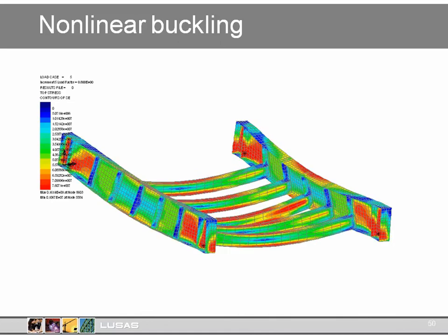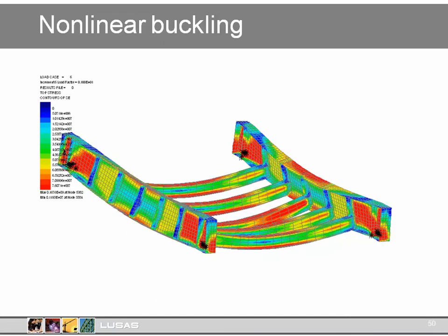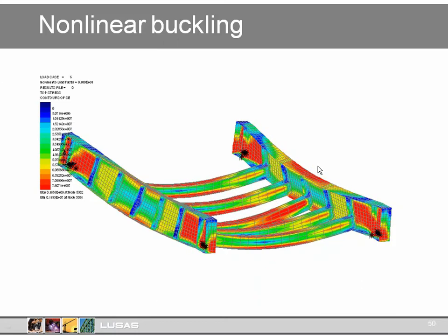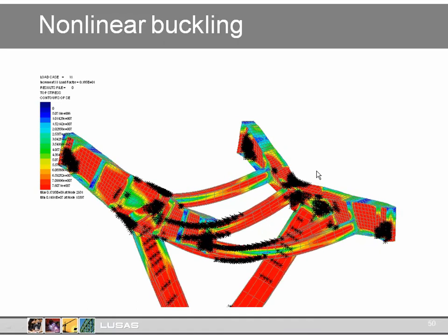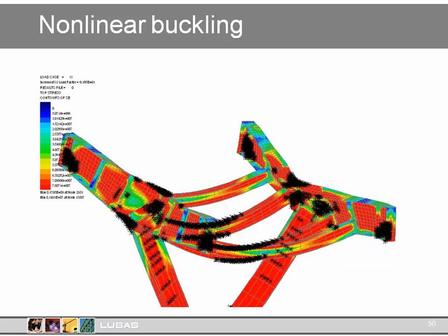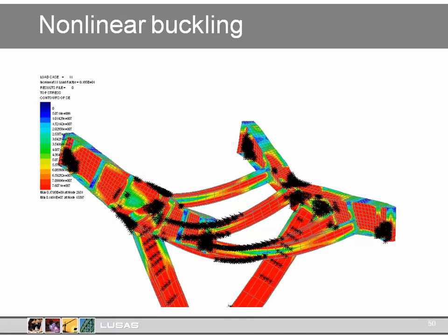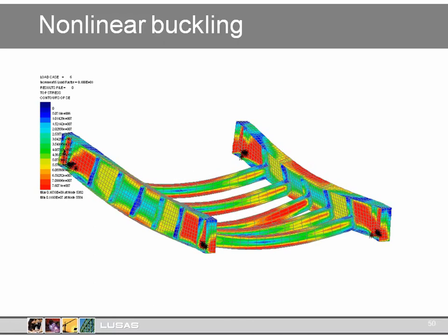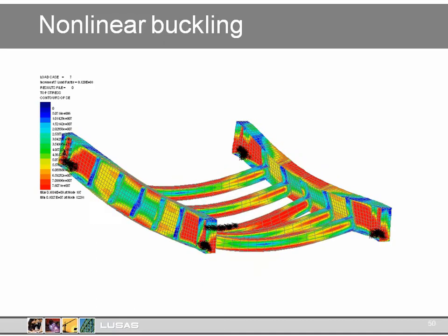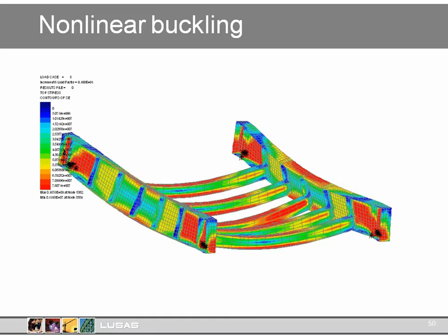And the final analysis can look something like this, incorporating geometric and material nonlinearity. In this animation, the black stars show where yielding is occurring. This kind of analysis, underpinned by a thorough understanding of finite element analysis in general, with preceding linear analysis and elastic buckling analysis, and the use of codes, can give us a good assessment of the real strength of a structure. We can use it appropriately, but with confidence, based on all that we have brought together and we can check our understanding of the structural model.